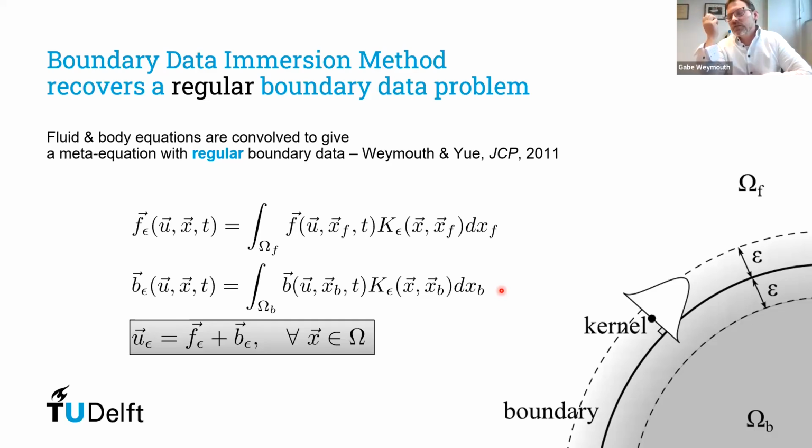data. So instead of going into a fitted grid method, kind of throwing out all of the advantages of the fluid subproblem on Cartesian grids, or doing cut cell methods or things like that, where we're sort of approximating fitted grid methods, we'll just change the governing equation a little bit. So we'll take that governing equation we had and we'll integrate it over a kernel. This is some little kernel function, and at any point, we'll integrate over whatever their local equations are. And there'll be some width to that integration, epsilon.